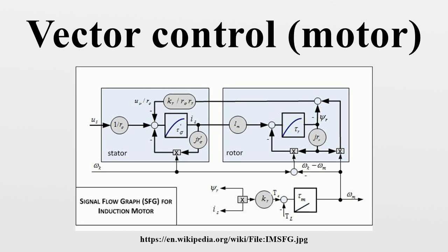7. Voltage components are transformed from the rotating coordinate system to the stationary coordinate system. 8. Voltage components are transformed from the two-axis coordinate system to the three-phase coordinate system or fed to the pulse width modulation modulator, or both, for signaling to the power inverter section. Significant aspects of vector control application. Speed or position measurement or some sort of estimation is needed.